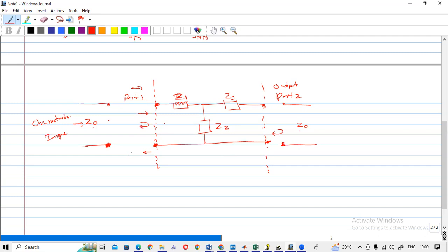So due to that scenario, we have to consider this transmission line impedance also, because when we evaluate the reflected voltage and forward voltage, we have to consider the transmission line characteristic impedance. Correct? If you have any question, you can ask.